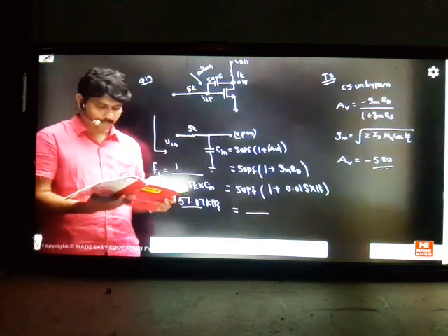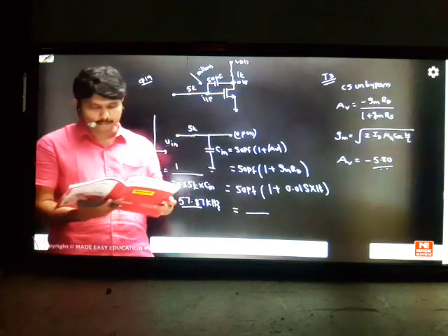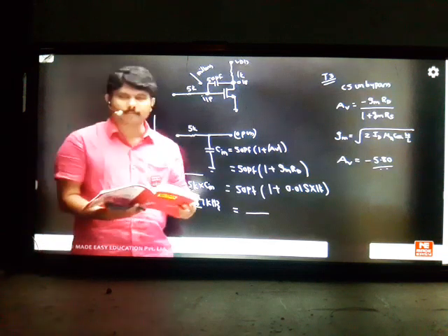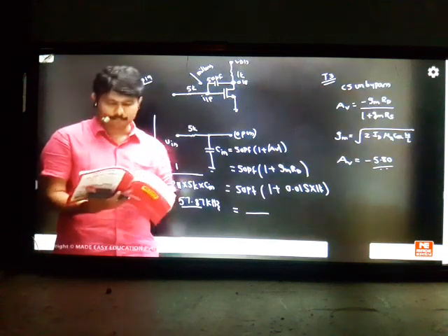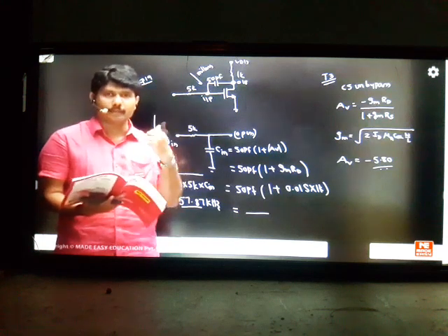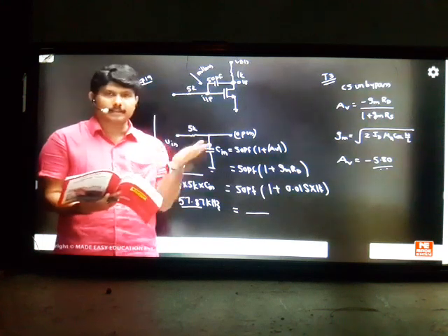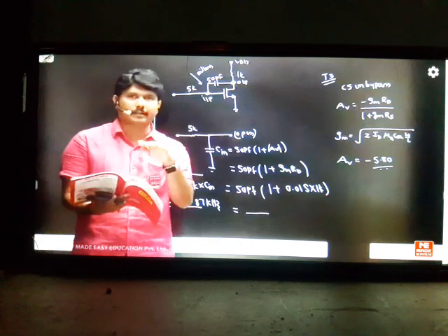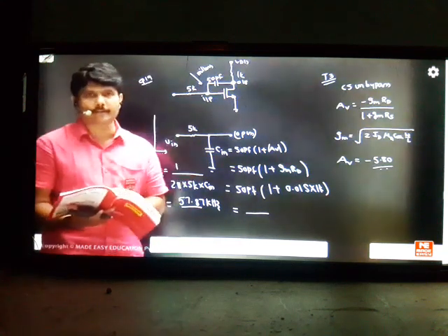Input he has given to the bottom transistor. He's asking what the gain of the circuit is. Simple question here. The bottom transistor is your Gm1 of the first transistor. Above is completely load for you. If you want that load, they kept the current mirror on the other side. That current mirror will bias your active load. Correct? So how much current this current mirror will send to the other side, and how much equivalent resistance you can draw for that. This is the actual question.